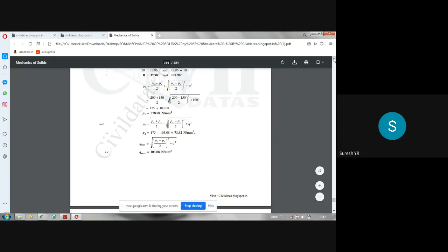Next, coming to maximum shear stress, they may ask you to find the maximum shear stress, Qmax, and also the direction of the planes on which that maximum shear stress acts. We have proved that the planes of maximum shear will be at 45 degrees to the principal planes. That also we have done. So those are the two types of problems. Today I explained one more problem in which a specimen is subjected to only tension, only compression, and shear strength is given. What is its failure load?